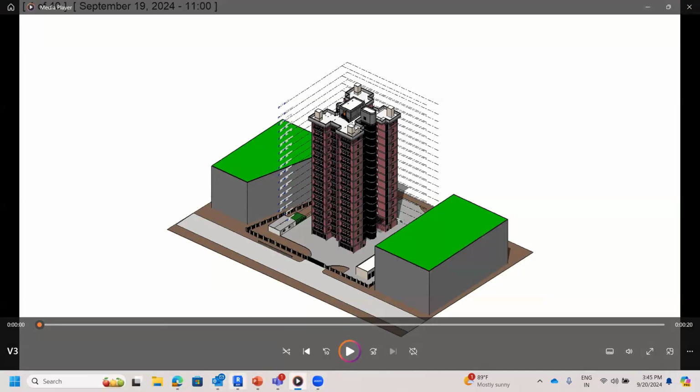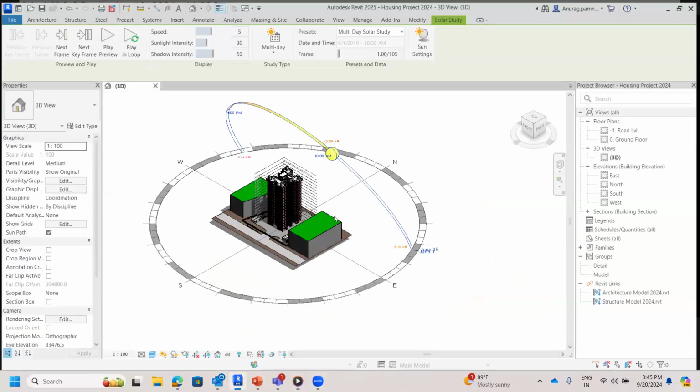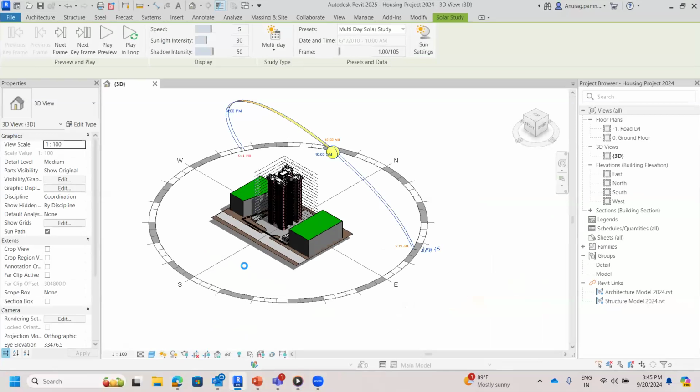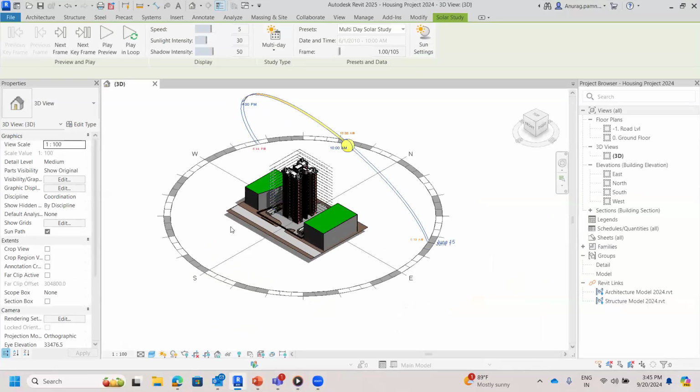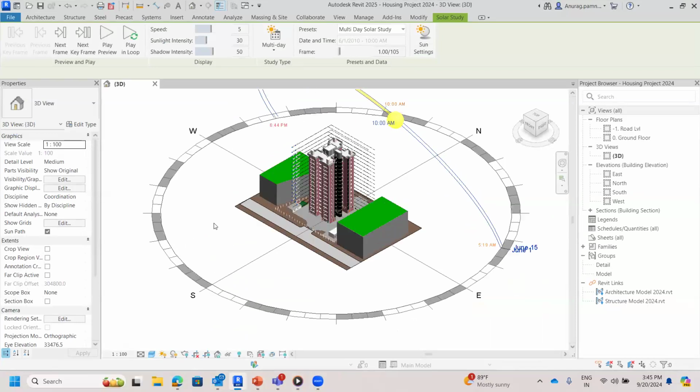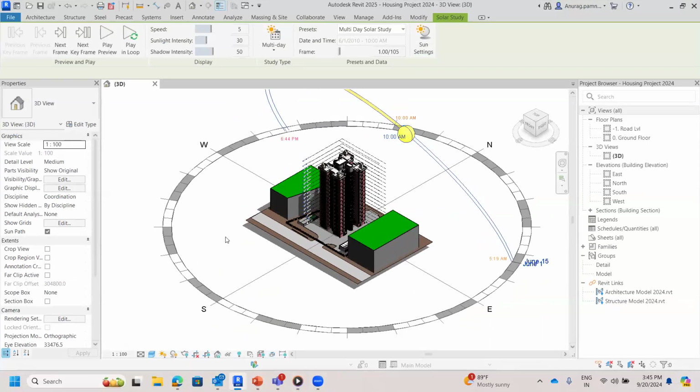So we'll now just take you directly onto the interface again, and we'll run a sort of illumination analysis, I would say, so that we can predict how much radiation is getting incident onto the surfaces of our building. We can also analyze that using a plugin which is available to us in Revit, which is a solar and illuminance plugin, both of them.